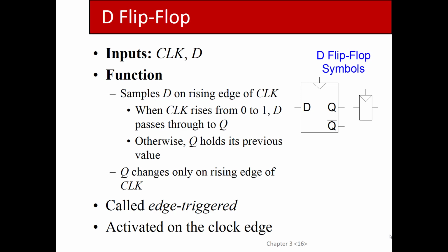The difference is that the edge of a clock is an infinitesimally small period, really, really tiny. I always think of it as taking a snapshot. Propagation delays and clock periods and all that stuff are relatively long periods of time compared to the transition time of a signal. As it goes from 0 to 1, it usually goes pretty fast. Now, it's not a square wave. It's not discrete. In reality, we know from chapter 1 that digital circuits are really analog circuits.